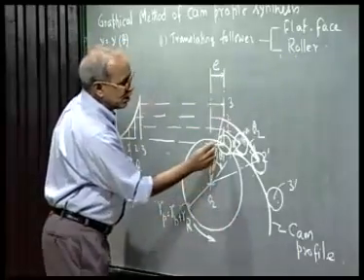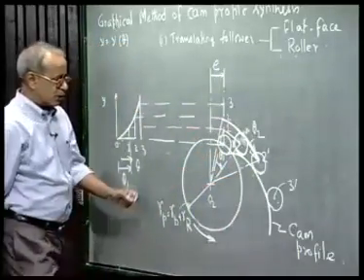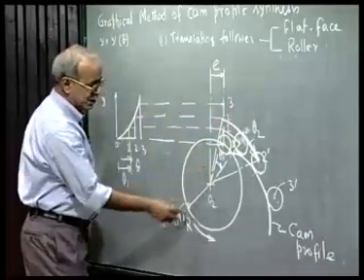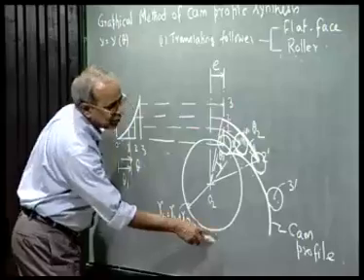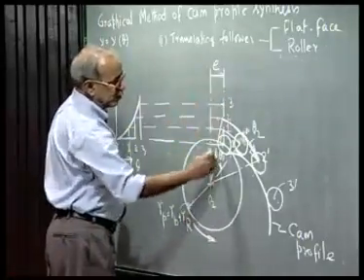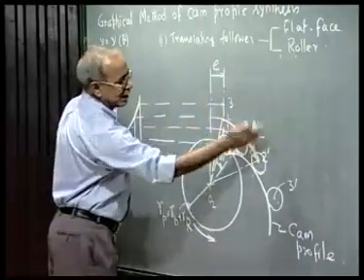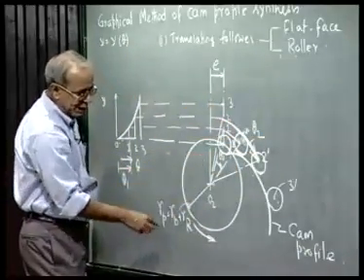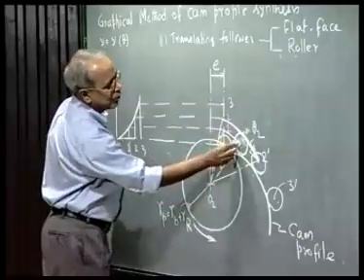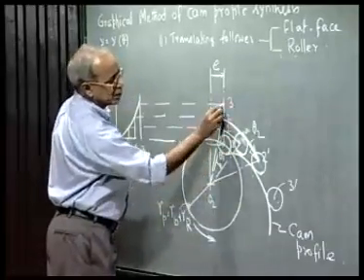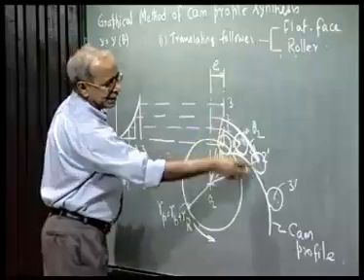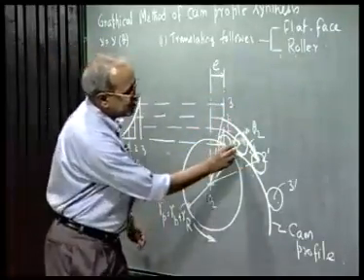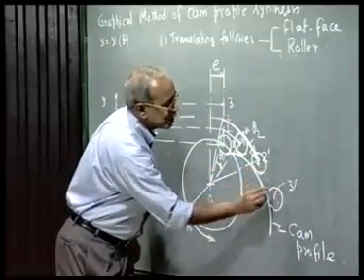So, this principle of kinematic inversion is very important: you hold the cam fixed and allow the fixed link to rotate in the opposite direction. The cam is rotating in the counterclockwise direction, so this follower axis for the translating roller follower is rotated in the clockwise direction. That rotation can be done very easily geometrically by rotating this line O2A1, O2-2, O2-3 by theta 1, theta 2, theta 3 in the clockwise direction. That gives me the location of this trace point of the roller centers.